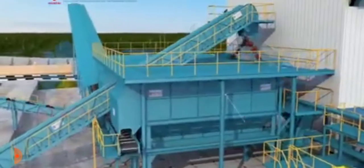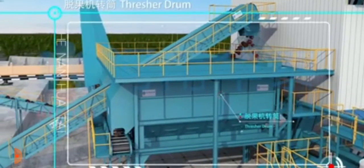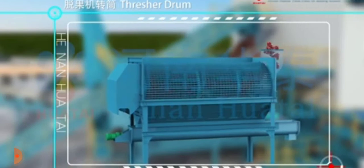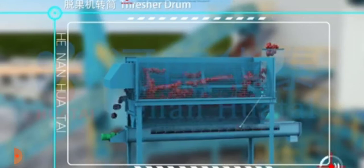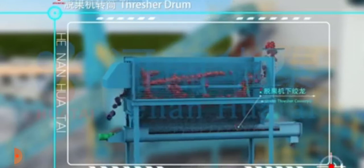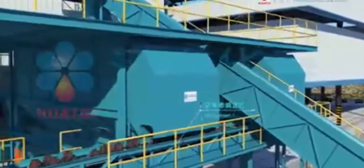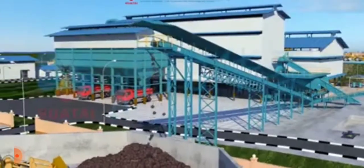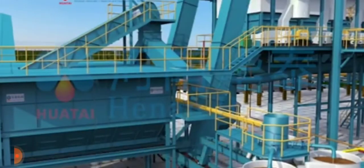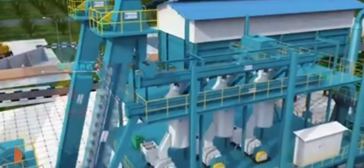Convey to the thresher drum. Fruit bunches rotate with the thresher drum through beating and falling. Fruits fall to under the thresher conveyor from the bunches. Empty fruit bunches discharge from the other side of the thresher drum and are conveyed to the EFB area by the EFB conveyor. Fruits are conveyed to the fruit elevator from the screw conveyor under the thresher.